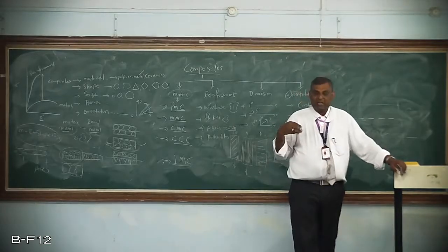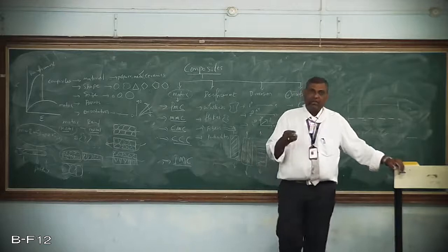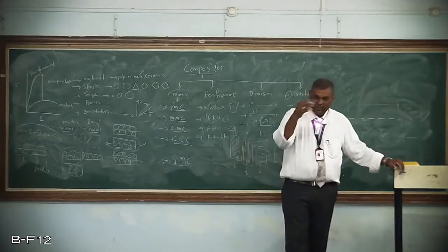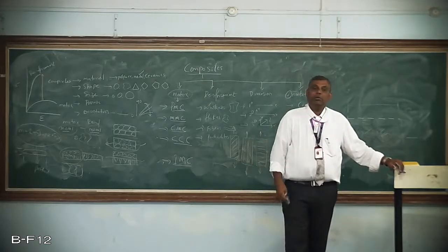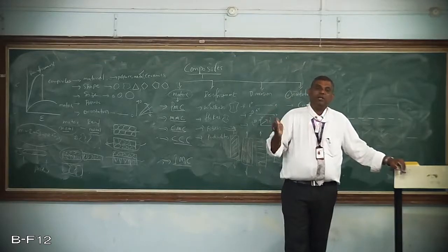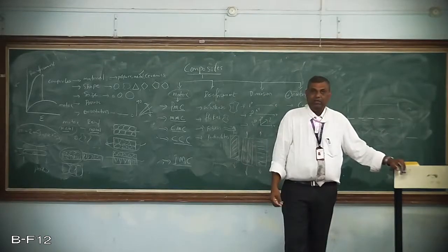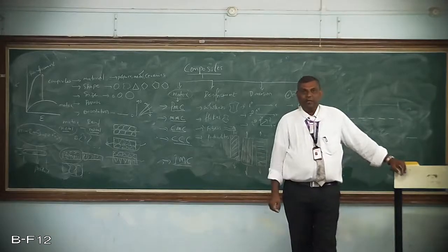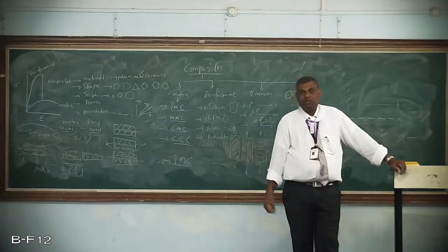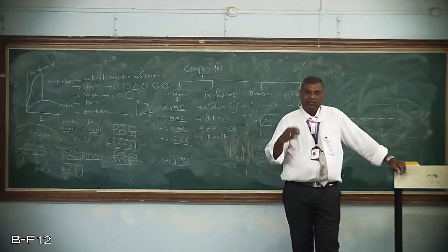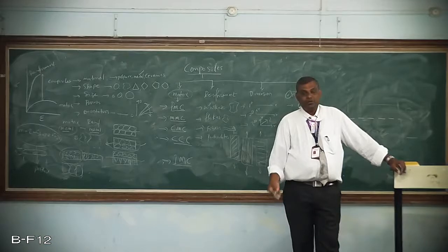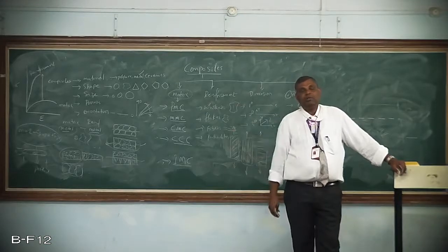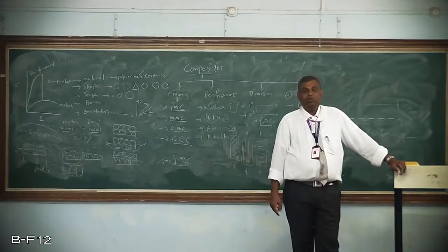Even if you do a secondary process like heat treatment, spray coating, galvanizing, nitriding, whatever process you do, you cannot enhance the properties to a significant level. You can only increase them to a considerably smaller limit. Now by making a composite, with the same elements but different processing methods, the strength almost doubles or triples compared to the base metal. That is the difference between alloying and composites.